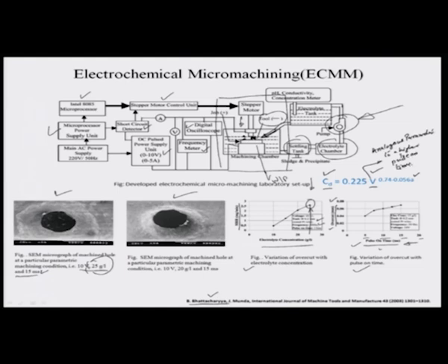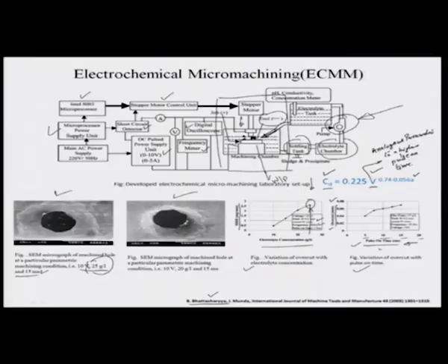So, you can think of it as if the electrodes are facing the voltage for a higher duration if the pulse on time is more in comparison to the pulse off time, and if the electrodes are facing voltage for a higher duration, the diametral oversize is going to get increased because of that voltage. Okay. So, therefore, intuitively also the overcut relationship with pulse on time happens to be quite well.